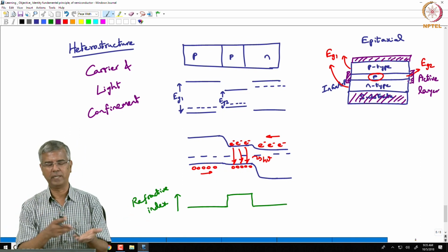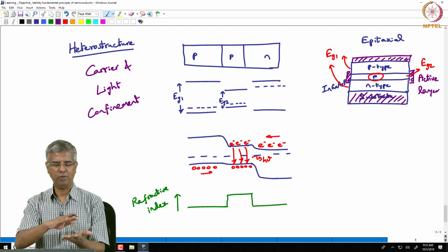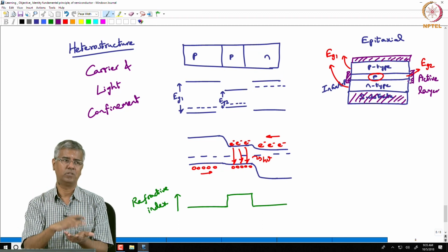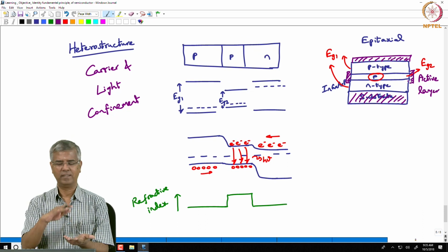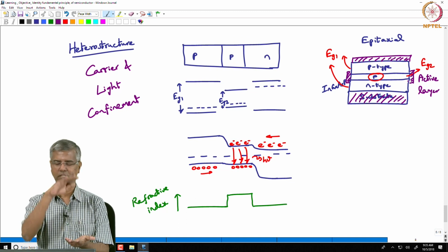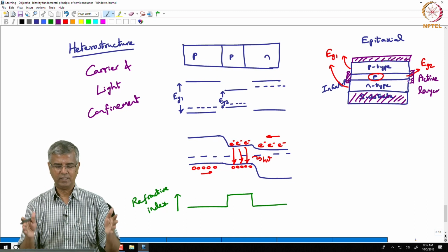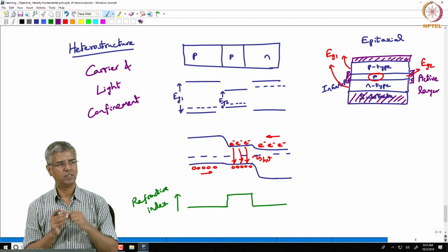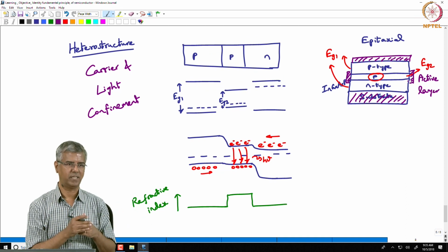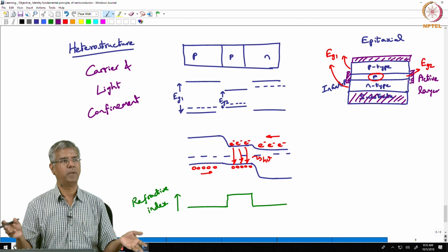These days you can do it on an 8-inch wafer or maybe even a 12-inch wafer. You build it epitaxially on a large wafer, which actually takes a lot of time, because you are talking about laying one atomic layer on top of another, right? It's a very slow growth. But then, each of these devices that you need is only like 100 microns in size, so you can dice it up into that many pieces.